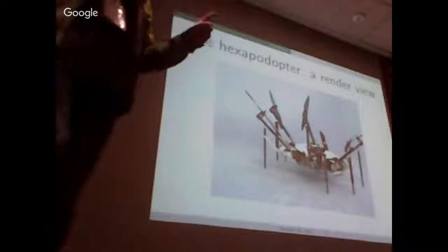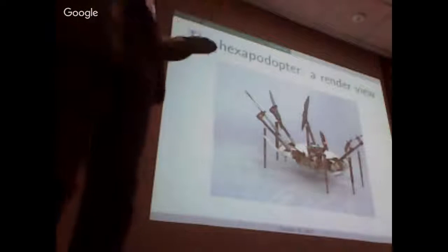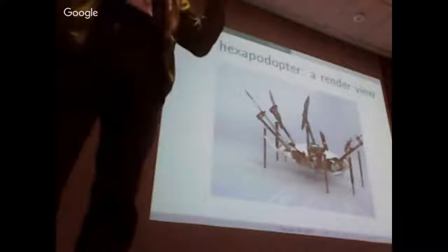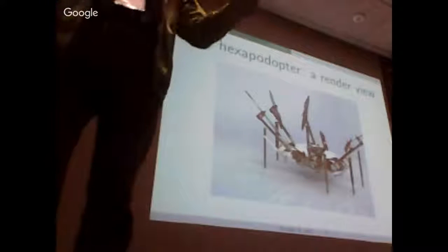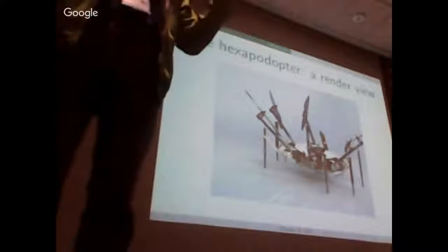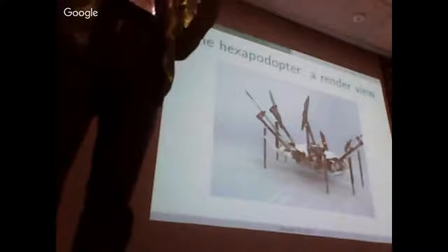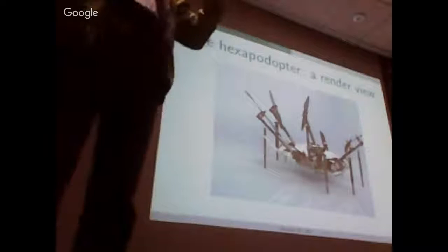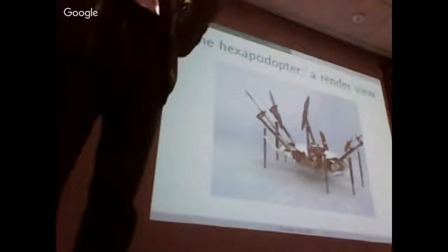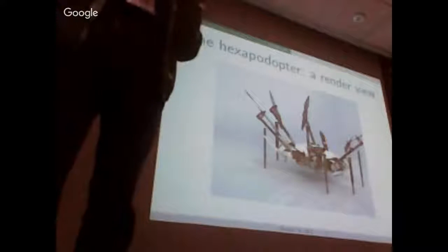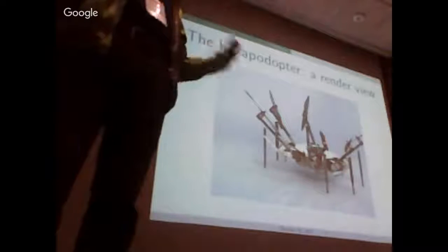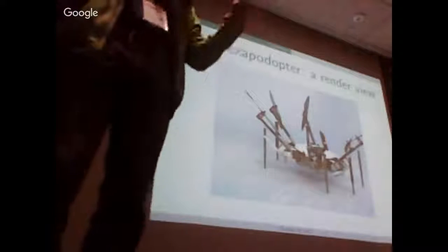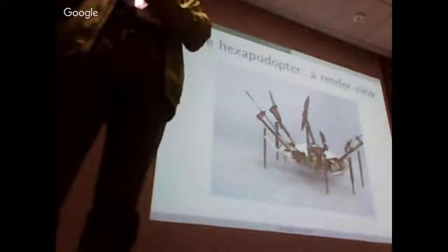The idea is that we can make this robot take the configuration of a standard vehicle with all axes of the motors being parallel. But we can also change the orientation of the motors before flight, and then once it reaches the 40 degrees that I showed you, it can pick up and perform holonomic flight.